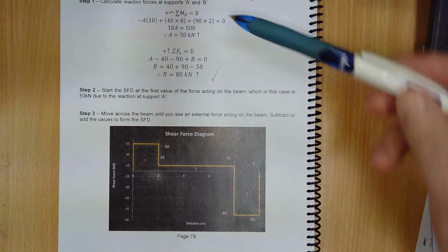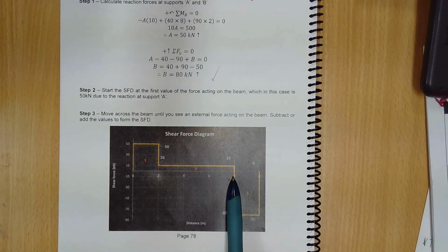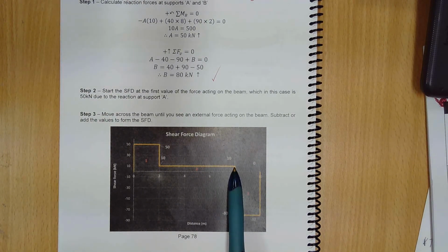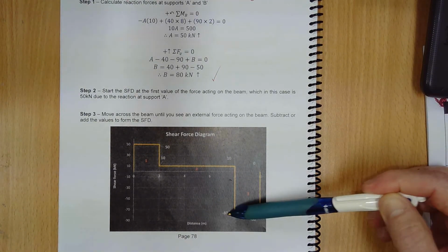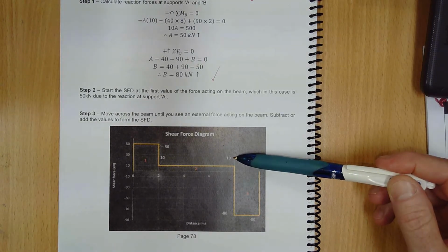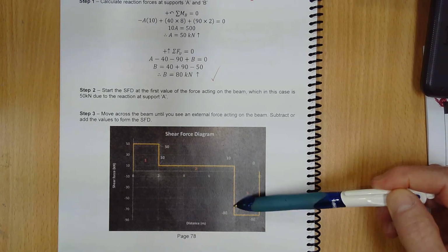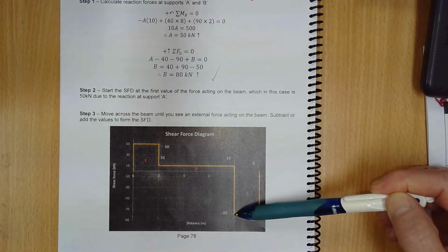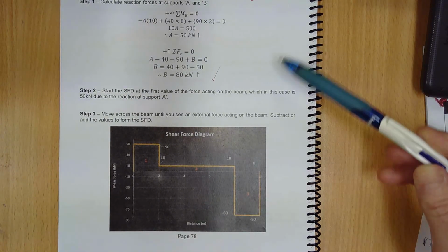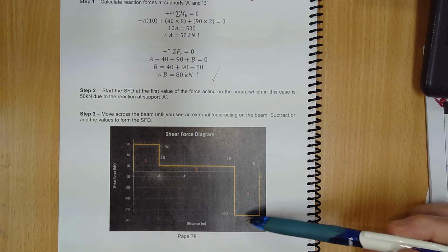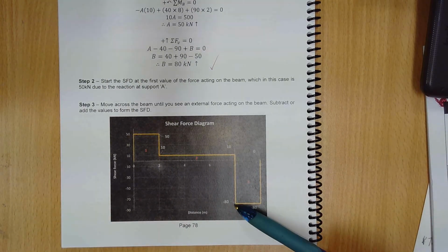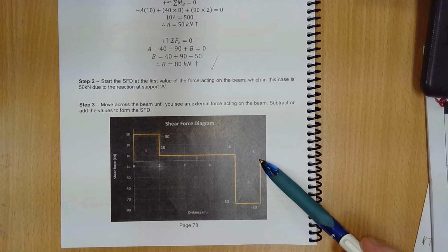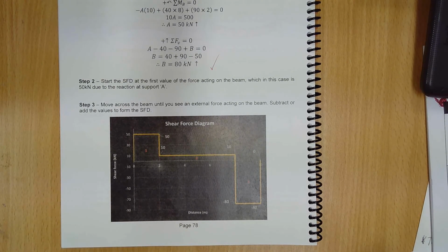The next force is the 90 force, and it's at the 8 meter mark. So if we have a look at that, 2, 4, 6, 8 meters. Okay, we've traveled straight across until we hit that 8 meter mark, and then we're going down again. Okay, that's to -80, but it's a distance of 90 kilonewtons. Because we've started there, we've gone down to -80 there, but there's 10 there, so that's the 90 kilonewtons going down there. The last one is the 80 kilonewton reaction that we're going to. It's another 2 meters along, so we travel 2 meters straight across and then back up to 0. We always know we have to finish on 0. So that's an example of our shear force diagram.